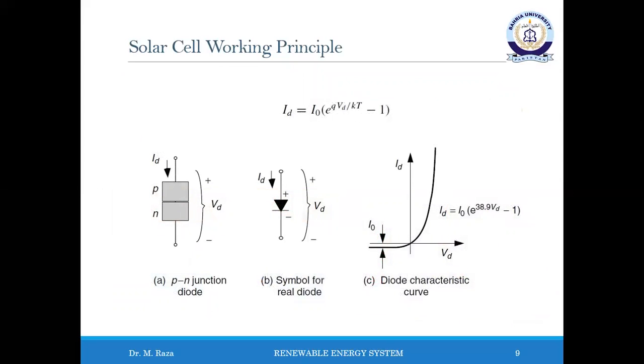The characteristics of a PV cell are typically defined using a conventional PN junction diode. The diode characteristic is shown in this diagram. If we were to apply a voltage across the diode terminals, forward current would flow easily through the diode from the P side to the N side.